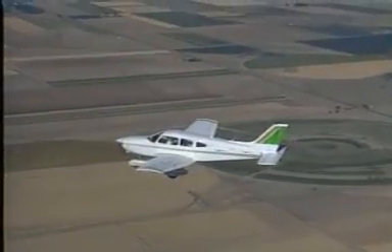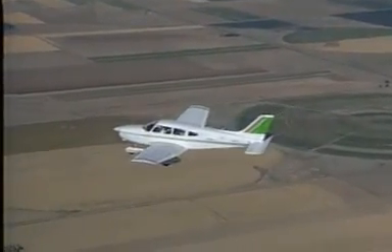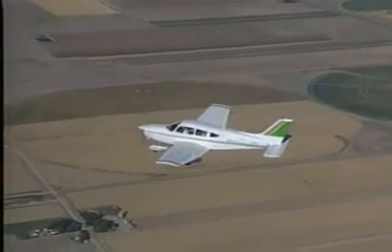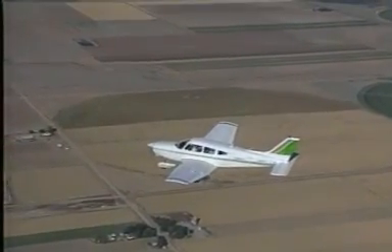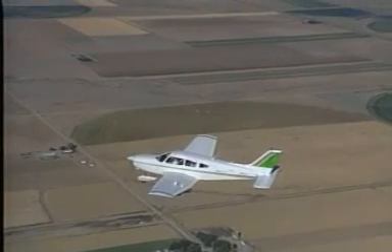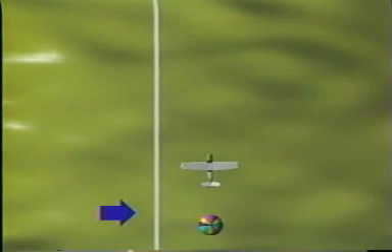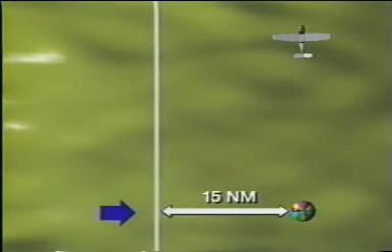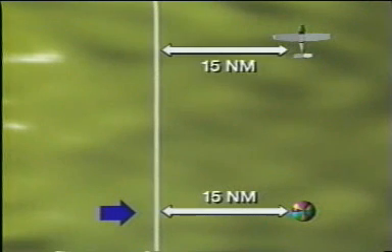An airplane is also influenced by the wind. While it doesn't drift freely like the balloon, it is deflected from its intended flight path and its ground speed is affected. To illustrate, suppose a free balloon is released in a 15-knot west wind. At the same time, an airplane begins a flight due north at 100 knots. After 1 hour, the balloon will have drifted 15 nautical miles to the east. The airplane, flying northward, will also have drifted this same amount.